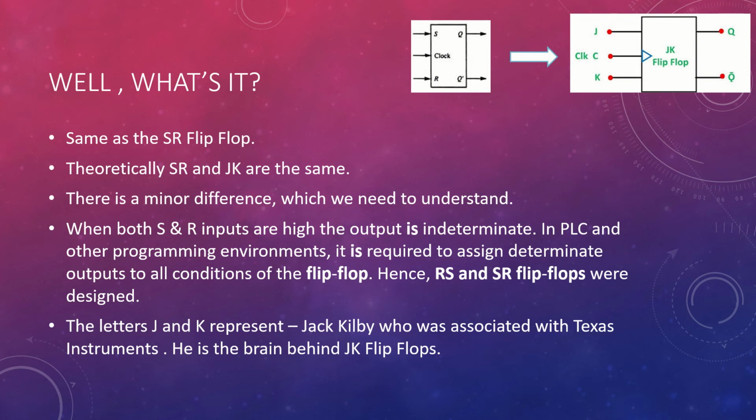This is same as SR flip-flop. Theoretically speaking, SR and JK are the same. There is a very minor difference that we need to understand. When both S and R inputs are high, the output is indeterminate, or it is non-existent, in the case of the SR flip-flop. But when you go ahead with PLC or other programming environments or infrastructure, it is definitely required to assign a deterministic output to all the conditions of the flip-flop. It cannot say that I do not have an output. It must have an output.